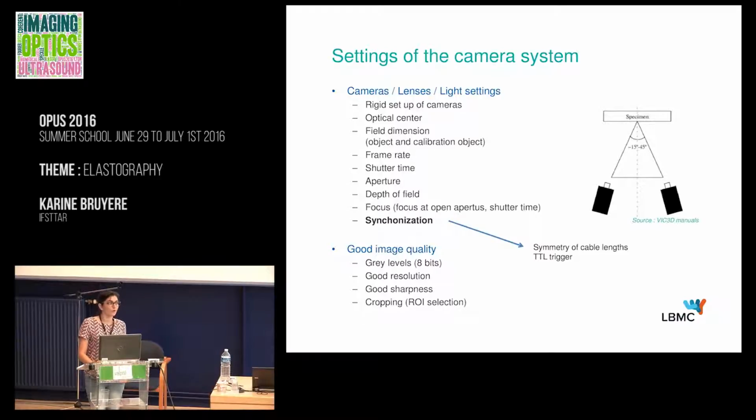It may be quite obvious, but it's very important in the case of dynamic tests too, to have very good synchronization between the two cameras. For example, we take care to have the same length of cables between the two cameras, and a good trigger of the cameras for the recording using a normalized signal.